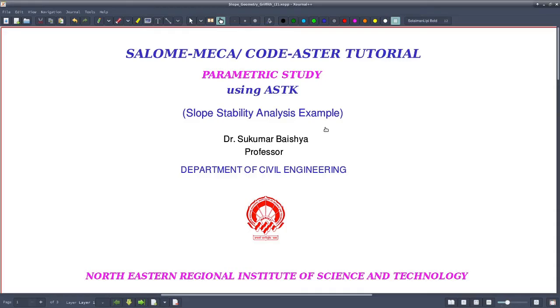Parametric study here means that in a simulation we need to use various parameters. Say, for example, if I analyze the deformation or stresses in some structural member, say I am doing elastic analysis, my input parameters will be modulus of elasticity, Poisson's ratio, then loads, then boundary conditions.